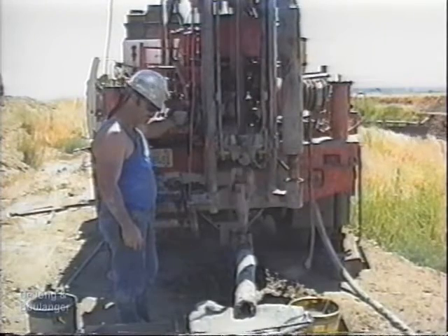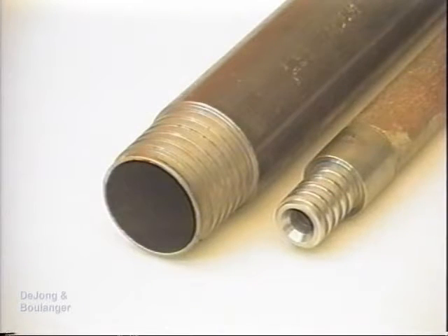Most drill bits can be modified to be side discharging by spot welding on baffles to deflect the drilling mud sideways. When sampling at depths less than 50 feet, A or AW drill rods with an outside diameter of 1 5/8 inches should be used. And for depths greater than 50 feet, N or NW drill rods with an outside diameter of 2 5/8 inches should be used. The heavier N or NW drill rods are recommended for the greater depths to maximize the transfer of energy from the hammer to the sampler.